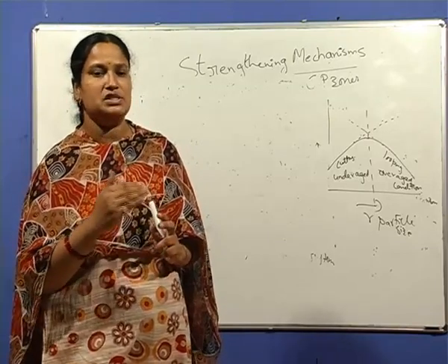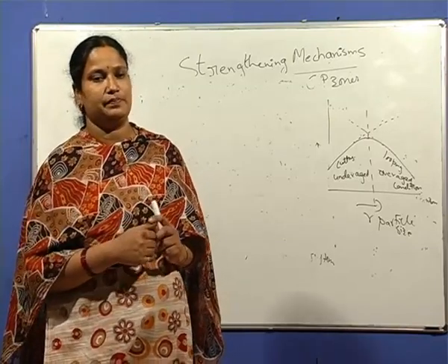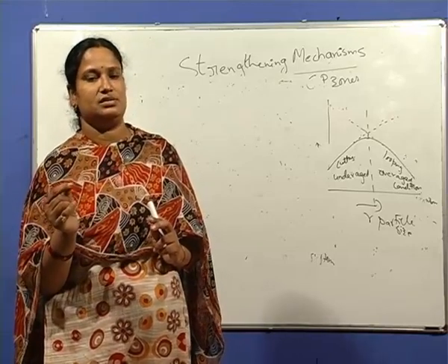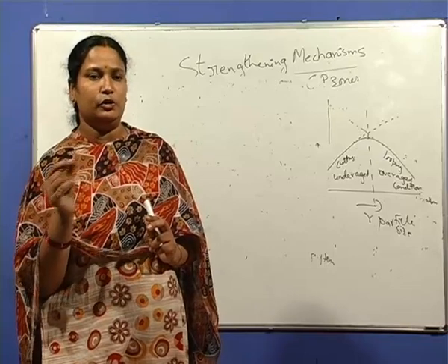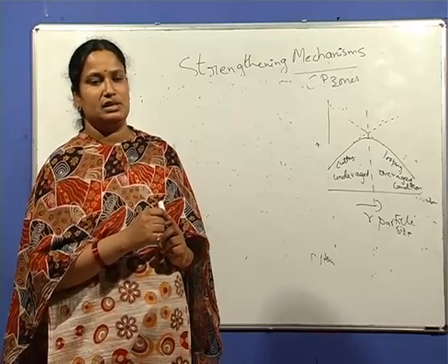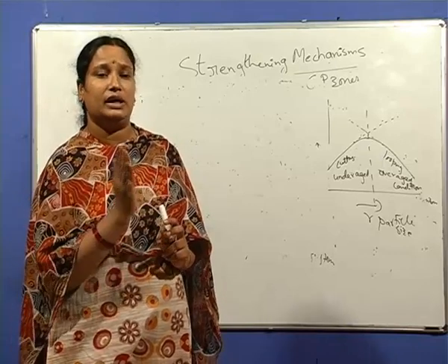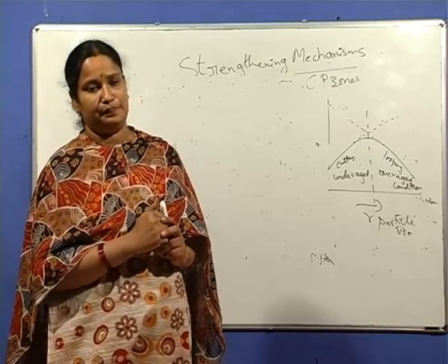It also transmits the load to the fibers. And any cracks which occur due to the breakage of the fibers, the matrix makes the crack tip blunt, so that the crack cannot propagate easily.